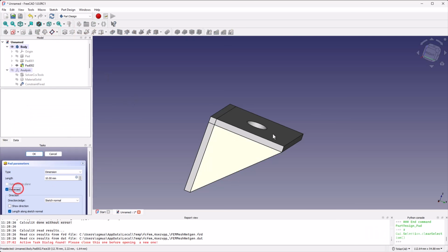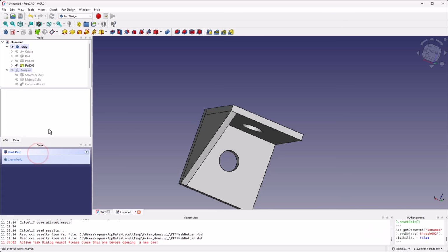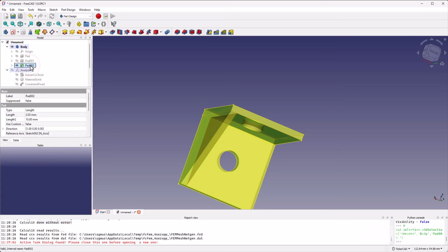We will reverse it so it goes inside, and we will make it 2 millimeters, or like we did earlier, about 0.08 inches, and that should calculate that for us. Notice we set the units here, and FreeCAD figures out how to convert those units to our document units, which is millimeters. So click OK. And if you click here, you can see the length given in millimeters instead.